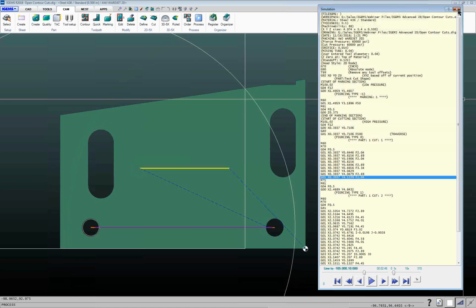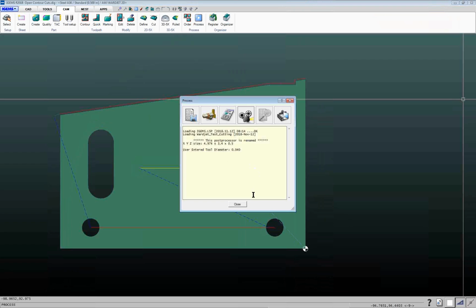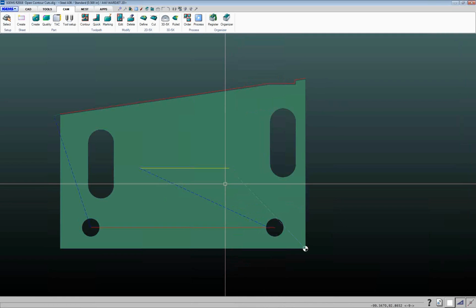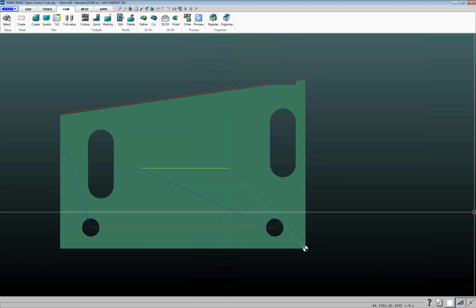If you have a pump that does not have that ability, then basically we can have it put M00s in the code at the appropriate point to stop the machine. Then the operator would go over and change the pump between low and high pressure.